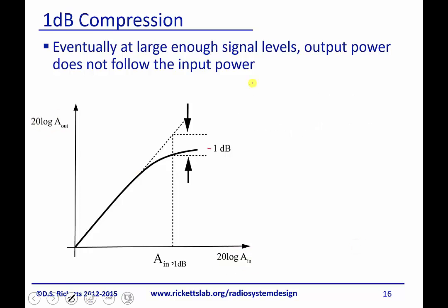All right, so let's take a look at this. If we have P out equals P in plus G, that's this linear line here. And if we want to find the 1 dB compression point, we just subtract 1. So we want to find the point where the P out is 1 dB below this. So if you remember, the gain is simply alpha 1 plus 3/4 alpha 3.